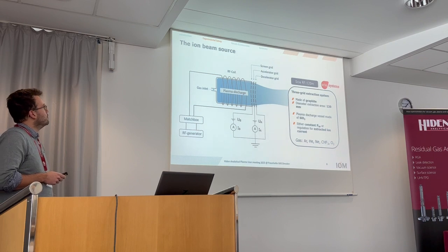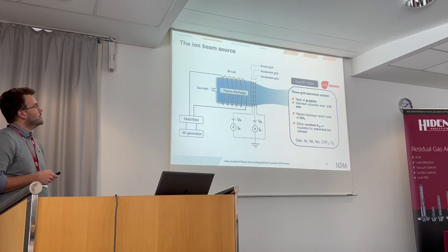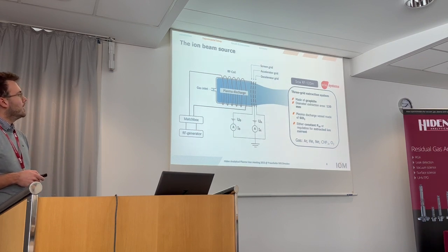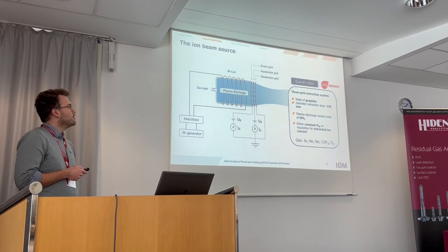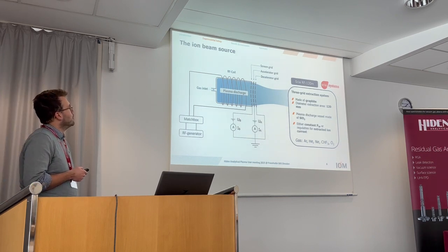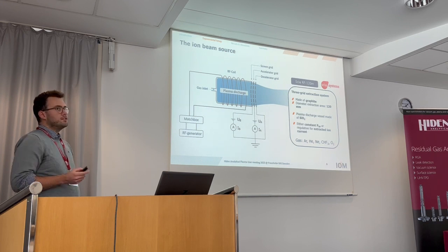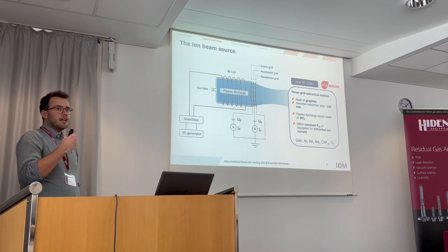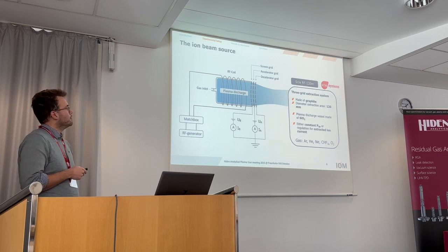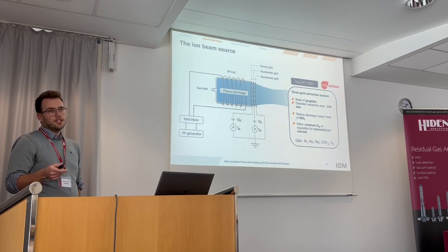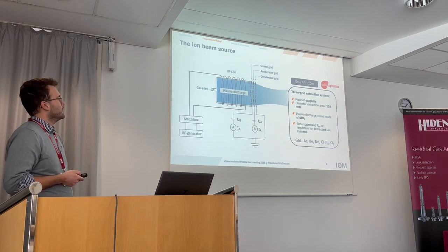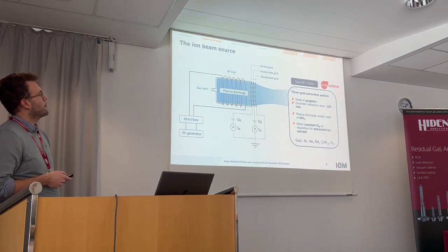So to the experimental setup, as I already said, we are using an RF excited ion beam source, which is an inductively coupled ion beam source. So we have our plasma discharge vessel, which is made out of silicon oxide. We insert our process gas, and by the surrounding RF cable, we are inserting energy into our gas to ionize it. Then we have a plasma, and this plasma is extracted with a focusing 3-grid extraction system, which is made out of graphite, by applying different voltages to it.